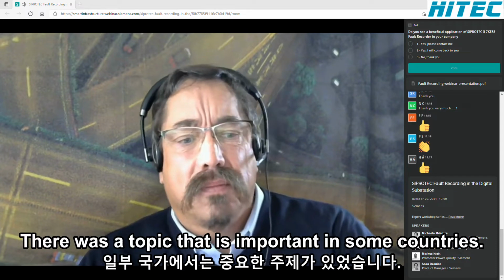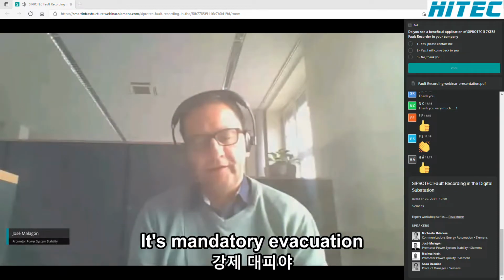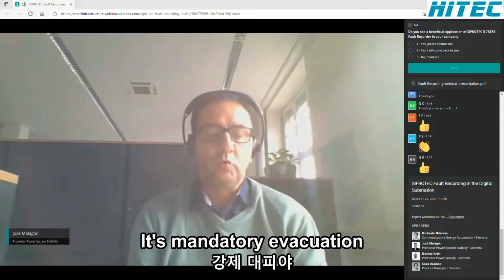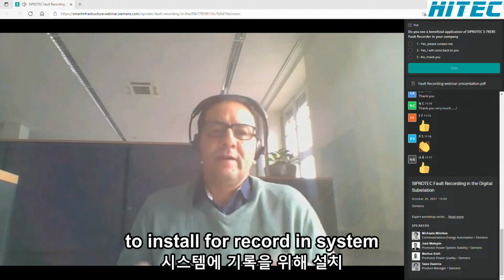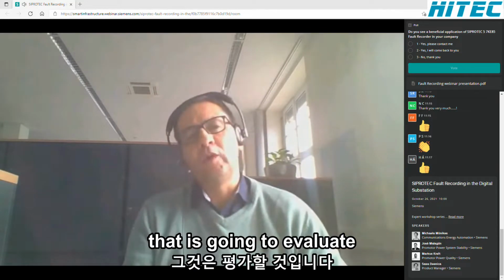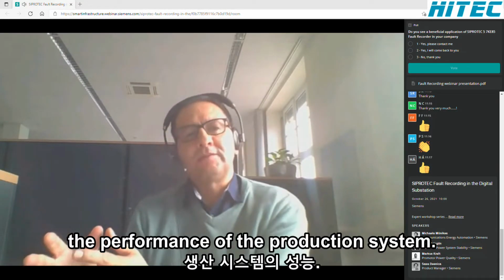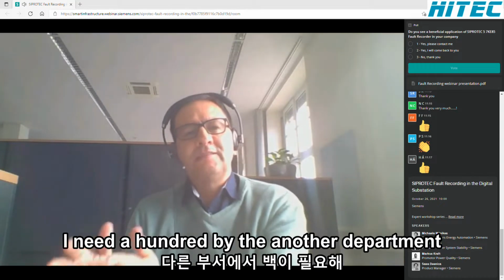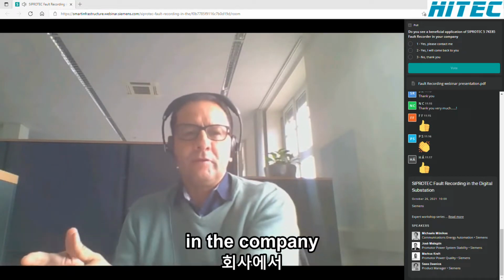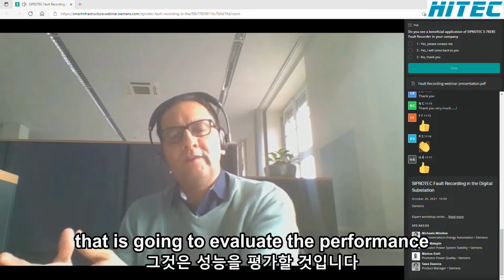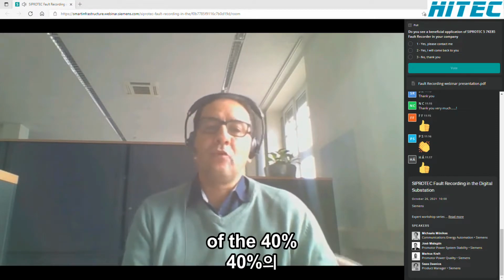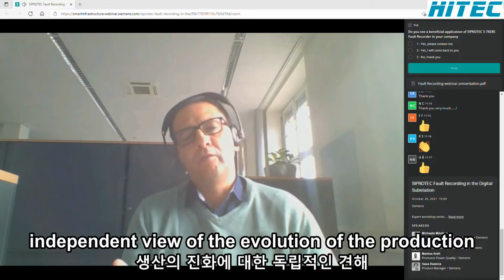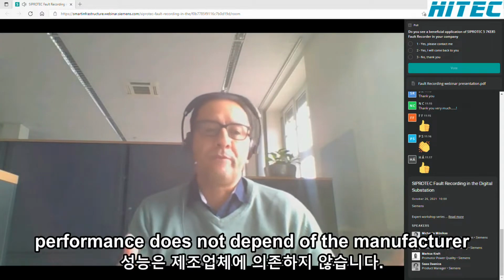The other topic here is important. In some countries, it's mandatory per regulation to install fault recorders. Then the customer prefers to have an independent system that is going to evaluate the performance of the protection system, handled by another department in the company. And that is the advantage of the fault recorder, that it offers an independent view of the evaluation of the protection performance.